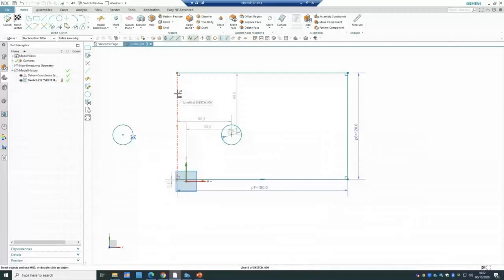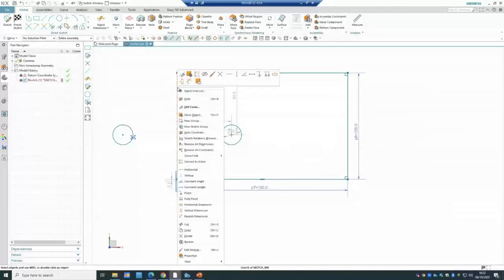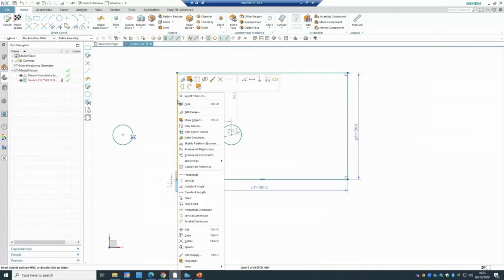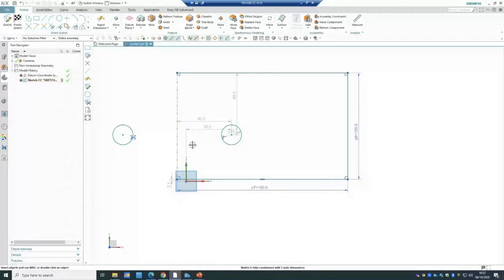From the previous session that I mentioned, we can always change an active line to a deactive, or center line, as we call it. You can always go there, right click, and find convert to active, or here. If I convert it to active, it becomes a line. If I want to make a line a deactive or center line, I can come here, click there, or convert it to the reference again. As you can see, a reference appears as the set of center lines that I have there.